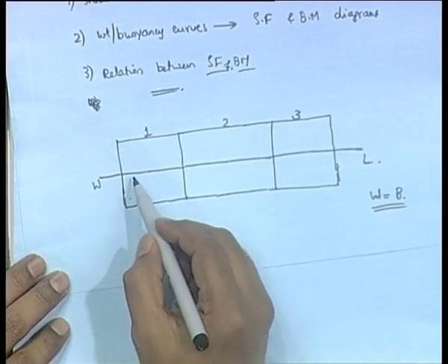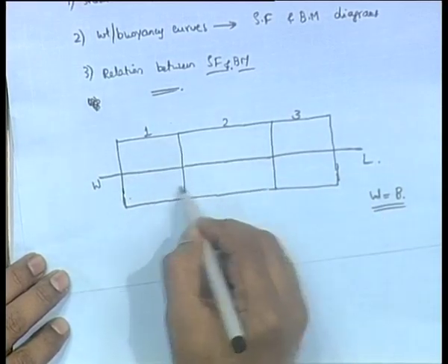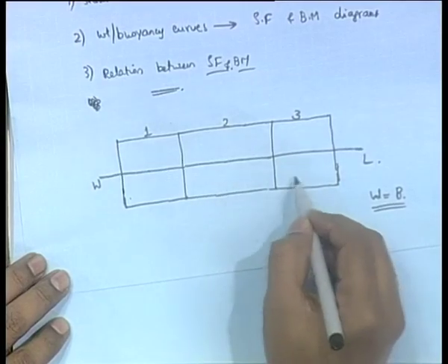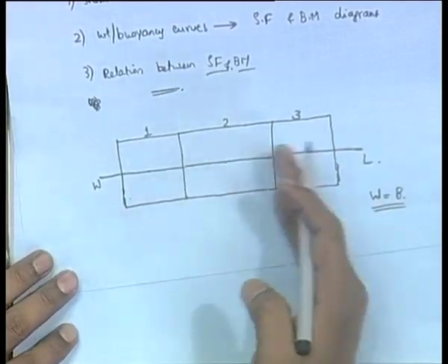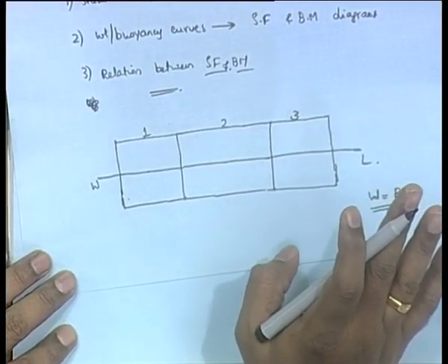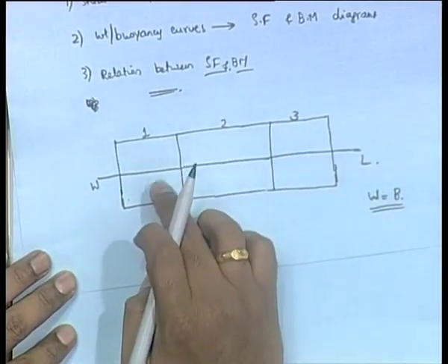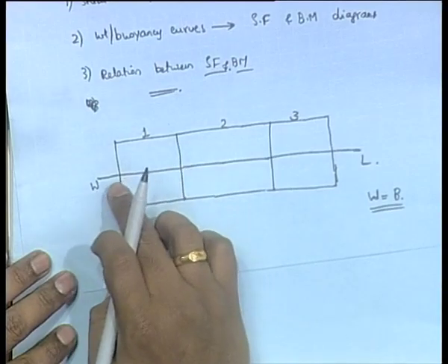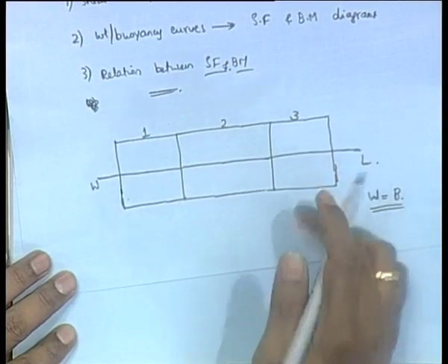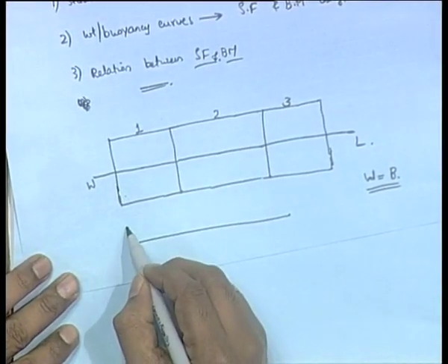Of course, in this case of a box shaped barge, if you have weight uniform, then the buoyancy uniform, then of course it is a very uniform case, and there is as such no asymmetry in weight or buoyancy, and the net load curve, I haven't explained load curve, but the net load curve or the difference between the weight and buoyancy curve will just be 0, it will always be equal. Means if I draw the weight curve, let us say that the weight curve is like this,